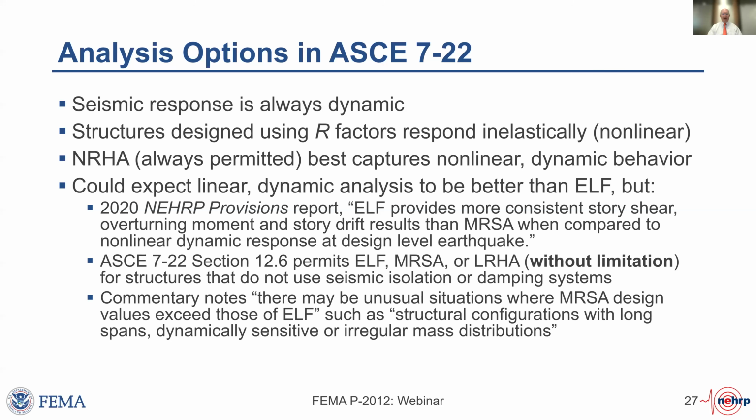And so that means that in ASCE 7-22, a change was made that allows the equivalent lateral force procedure without limitations for structures that don't have seismic isolation or damping systems. And where there are those other systems, there are some limitations, but ELF is still permitted. The caveat here is this study and other studies do find the ELF to be conservative, but you probably could somehow dream up a building where modal response spectrum analysis could identify something that ELF misses. And so there's just that caveat kind of hanging out there. We're not suggesting that you stop using modal response spectrum analysis, but know that it is less conservative than ELF.